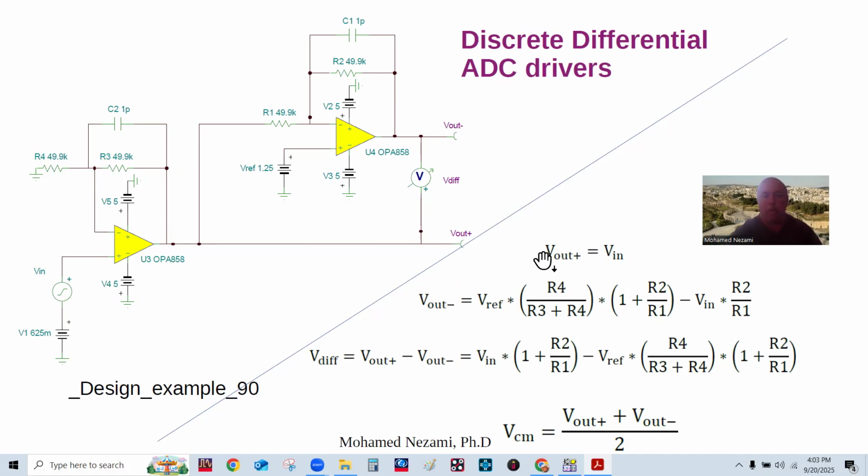Now, the Vout in here is presumably Vin, although in the way this diagram is, it's really twice Vin, because you have a gain of 2 coming from here. And then, of course, the DC offset that comes out of here, in this case that I have here, when I drew this, this was 0.62 volts in here, and that also has a gain of basically 2, so that's 1.5, and that's why I have 1.25 in here, and this is 1.25.